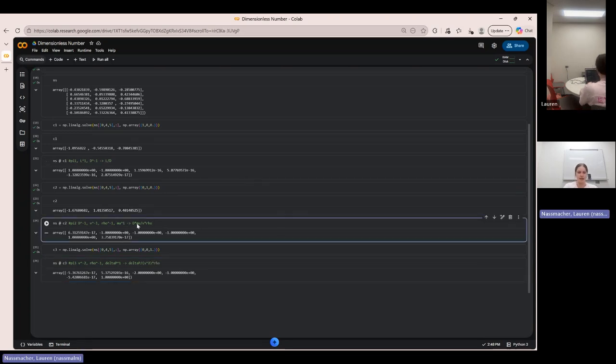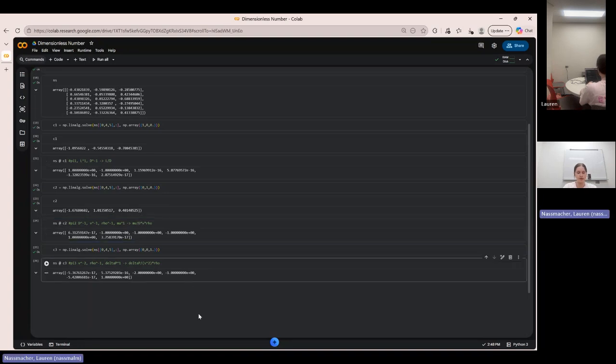And let me just edit this. This is actually, our diameter is going to be on the denominator. So here we have our final equations, our dimensionless numbers. None of these numbers have dimensions for our Buckingham Pi method for a pipe. So there you go.